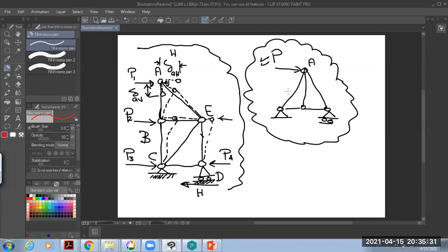For this, the mechanism and steps: calculate all the internal forces due to this external load, whatever the value of this external load, and go again, apply a unit load in the same direction as the external load. Unit load 1, no units, just 1. And calculate as well the internal forces due to this unit load.